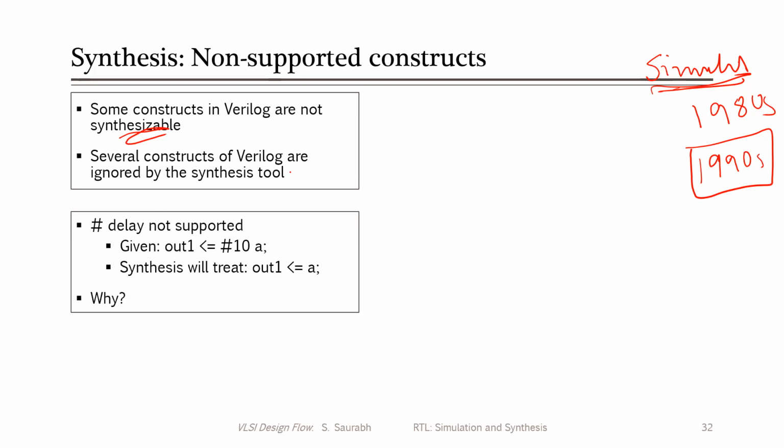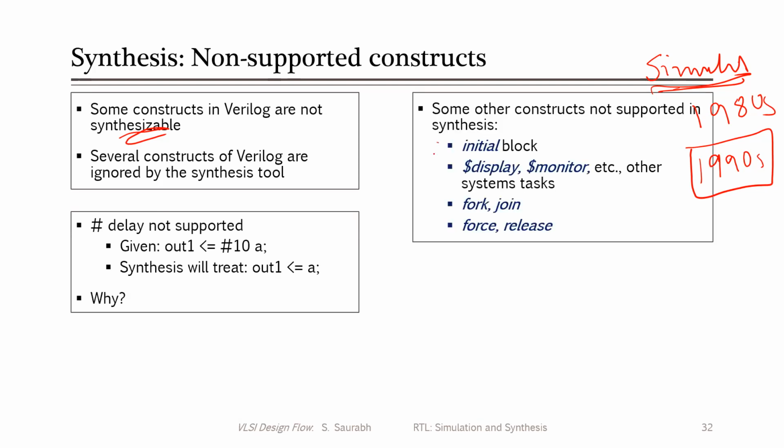Now, what are these constructs? For example, the initial block will not be synthesized in Verilog. Then there are display and monitor statements, fork-join statements, and force-release statements. These statements are not synthesizable. They are not supported by the synthesis tool. They will simply ignore these statements. Then another thing to note is that wherever you write delay statements, these delay statements are basically for simulation. These are not for synthesis. Why?